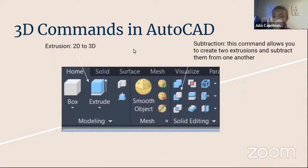Okay, so I only selected a few of these to go over because there are a lot, but honestly, I haven't even used a lot of them. If you're just starting to use AutoCAD, then these are the ones that you would be using. So extrude right here, this is how you go from a 2D to a 3D object. If you draw a rectangle and you want to make it into a rectangular prism, you would select the object and then extrude it. You can set how high you want to make it, and that would obviously be the height of your object.